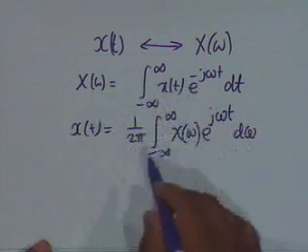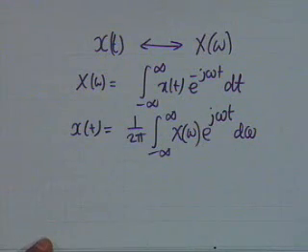We also considered the question of existence and convergence of the Fourier series. We basically discussed two types of conditions. One is that the signal is an energy signal, and the other is that it obeys Dirichlet conditions. One contains integrability of x of t mod squared, and the other contains absolute integrability of x of t mod, in addition to two other conditions on maxima and minima and discontinuities. Alright.